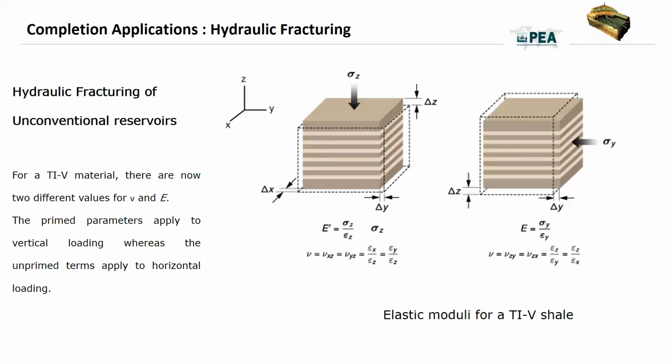So as you know, nowadays aggressive exploitation of the shale gas reservoirs in North America has highlighted the importance of the elastic anisotropy on the hydraulic fracturing simulation. Before, we tended to use only isotropic estimation. So we thought that all reservoirs are isotropic, and we designed our hydraulic fracturing to be isotropic. But a lot of information gathered from the unconventional reservoir exploitation in North America, in Argentina and China, has shed light on the importance of using the TIV